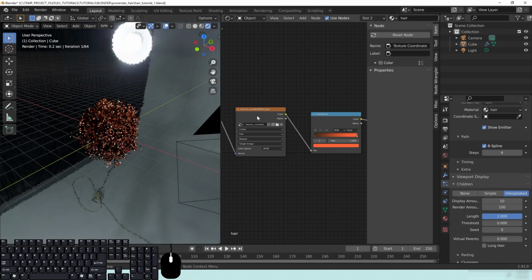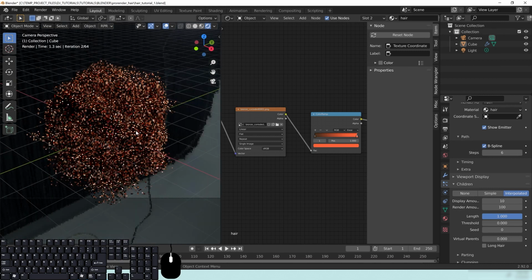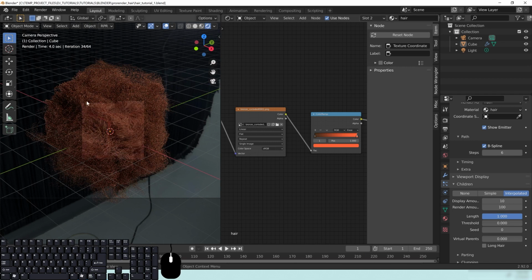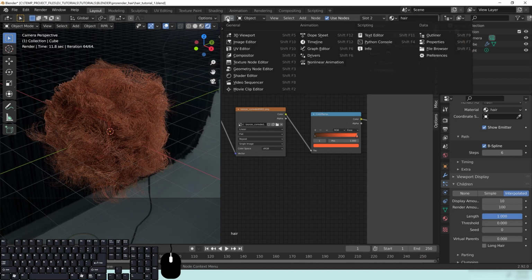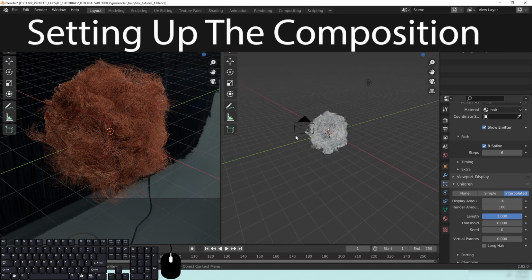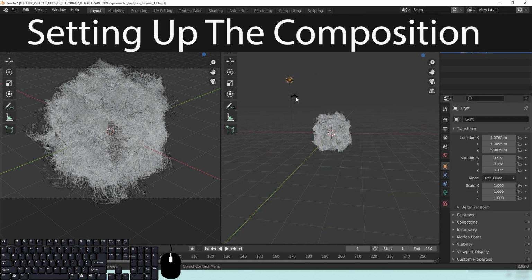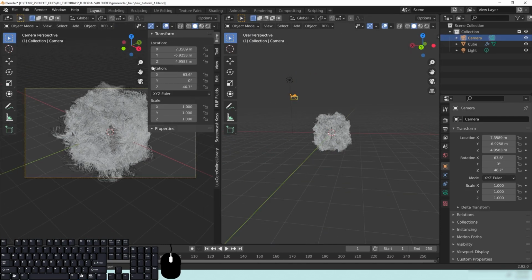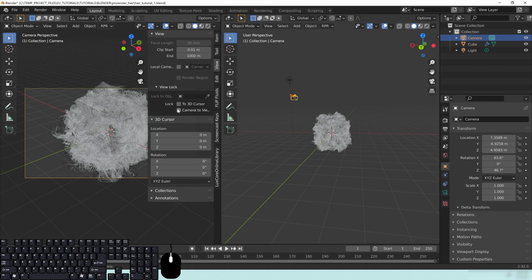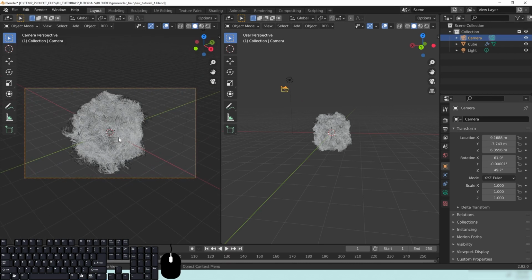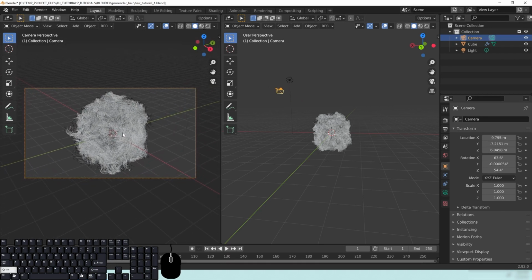So the next thing that you really want to do is set up proper lighting. So this is obviously not something that I would recommend that you do as a final. It's more of testing and checking and seeing how your materials are ending up. If you go up here to the 3D viewport, we'll actually change this to a solid view here. And I'm going to take the lamp, and let's do this. Let's hit N. We're going to go to view, camera, lock the camera to the view right here so that we can kind of move around this object and get it in our frame.